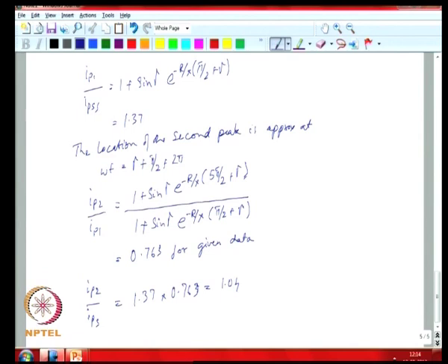So, you have to give allowance for the peak current that can potentially flow, because if a breaker is opening and a high level of current is flowing, the amount of charged ions in the gap when the breaker is separated would be proportional to the current. Okay. So, it needs to have the capability to interrupt whatever peak can potentially flow.